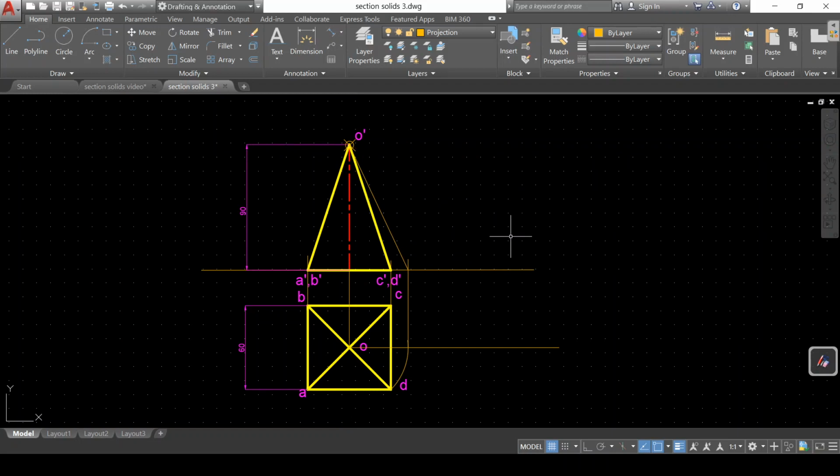So this is that true length now in the front view. This is the line that we have got down. This is of true length of this slant edge because we have made the top view of this slant edge parallel to XY. So this is the front view giving you the true length of this slant edge. Now we will develop this lateral surface taking this as the true length.